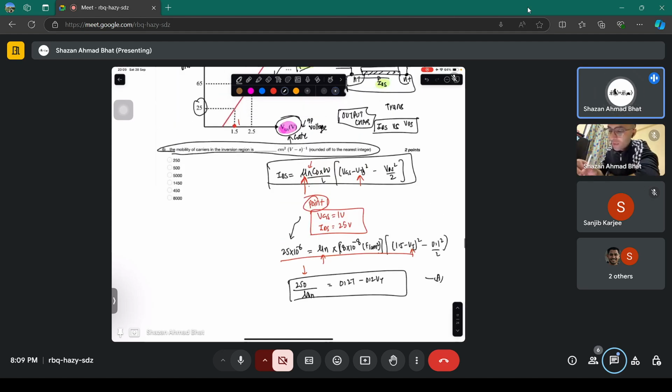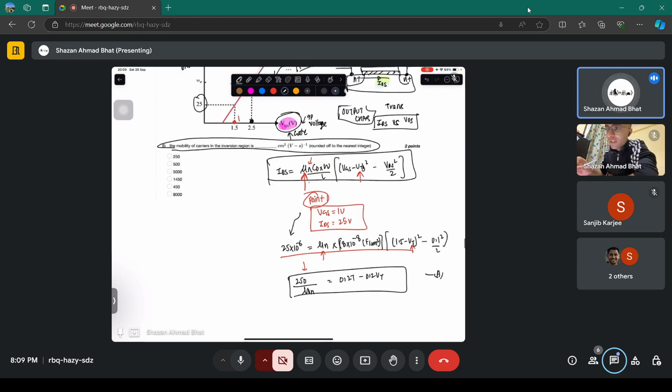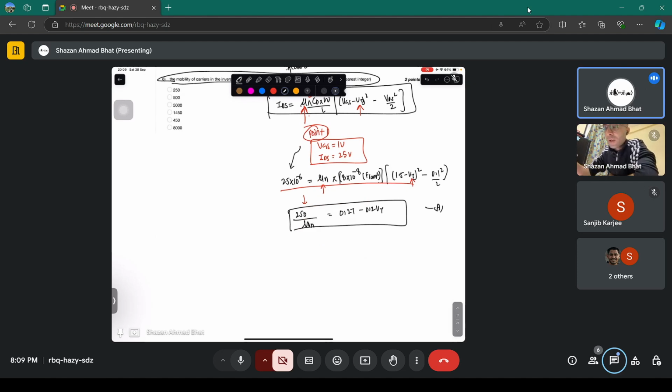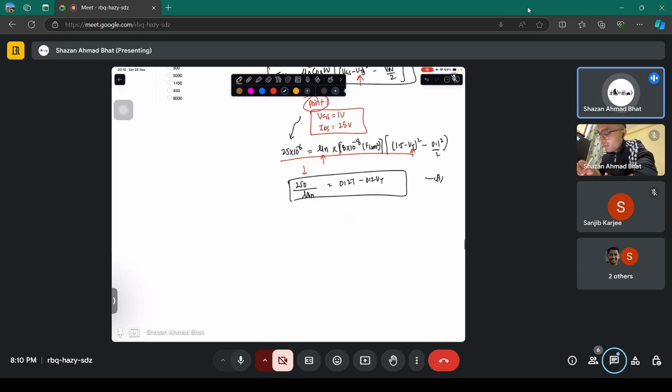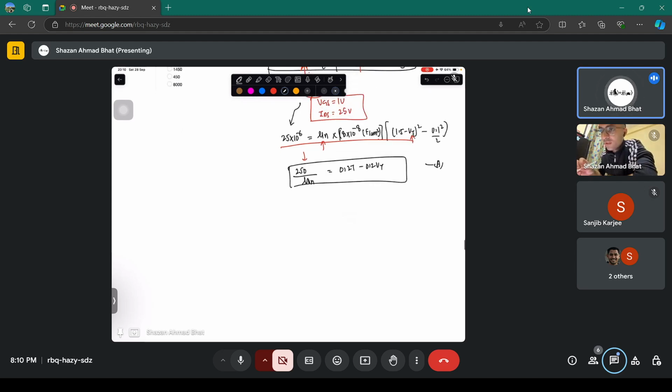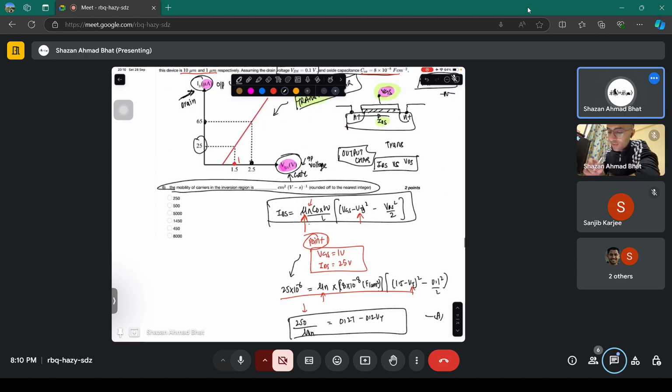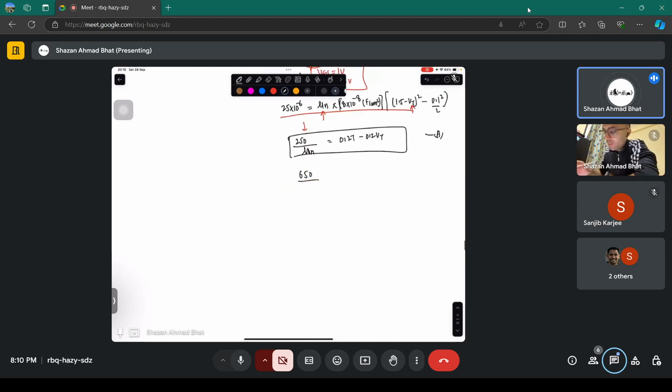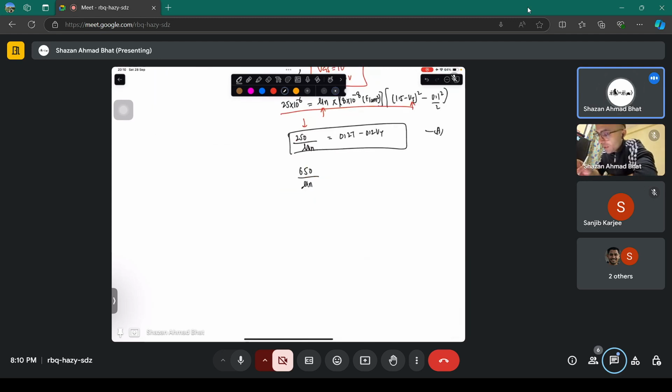Again, you have to solve at this other point using the same fundamentals. Because you have two variables, you need two equations to solve it. Using these values, you get the other equation: this quantity is equal to 0.49 minus 0.2 times Vt.